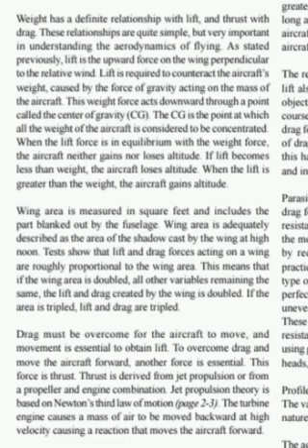As stated previously, lift is the upward force on the wing perpendicular to the relative wind. Lift is required to counteract the aircraft's weight, caused by the force of gravity acting on the mass of the aircraft. This weight force acts downward through a point called the center of gravity.